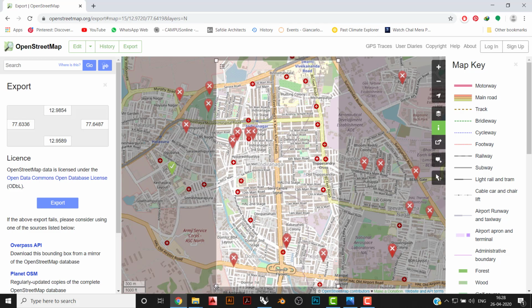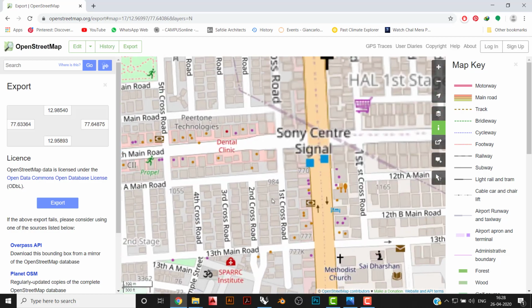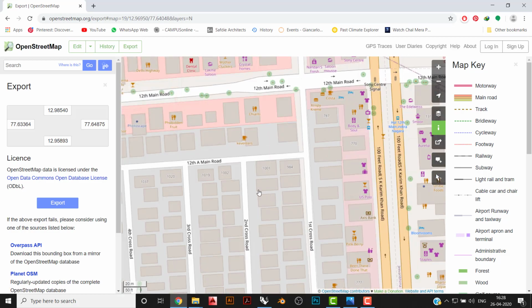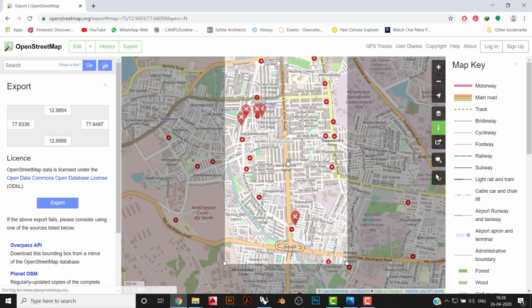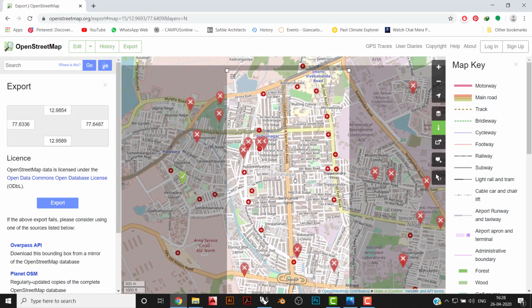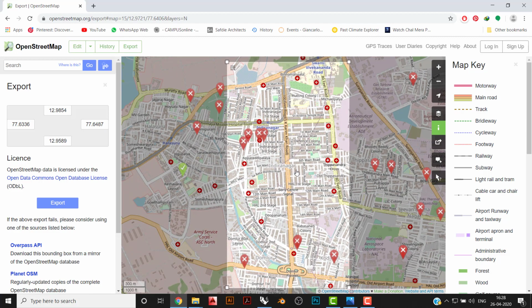Mainly you need to keep in mind that whenever you're using OpenStreetMaps, these days they updated, and we need to have only 5,000 points. Points means every building, let's say every box here, has 4 points because they have 4 corners. So we need to take below 5000 points. If we take above 5000 points, we'll get an error.